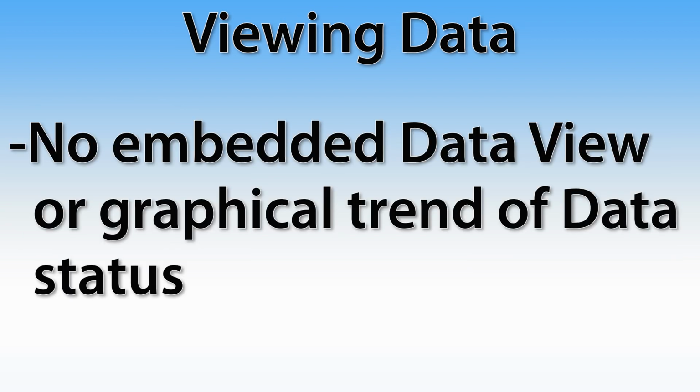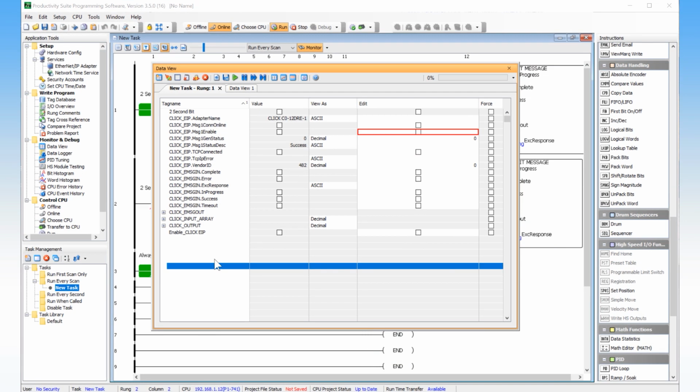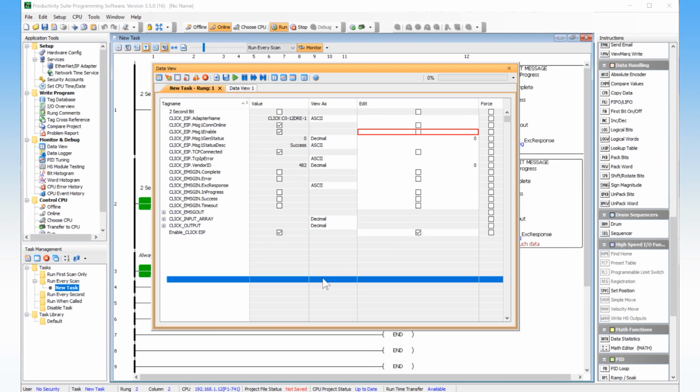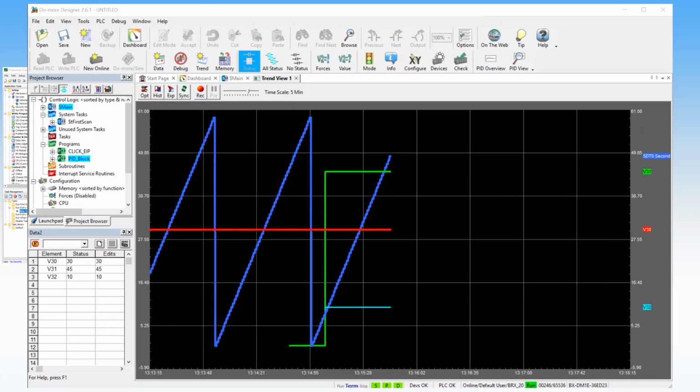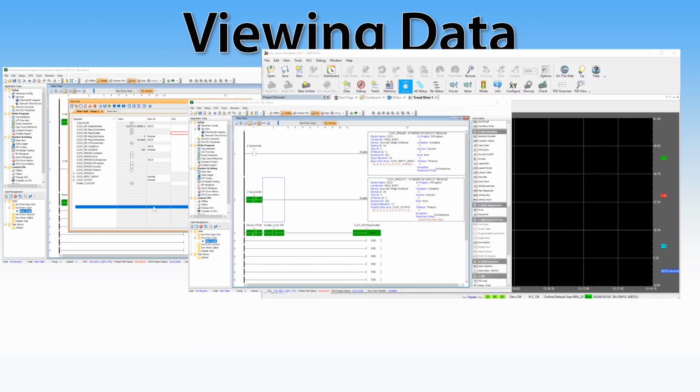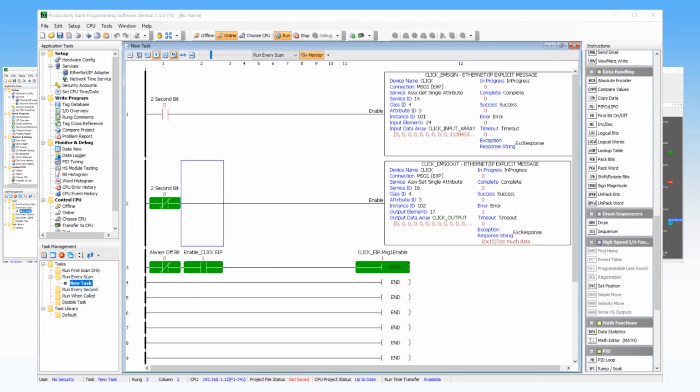Next is that the Arduino does not have a true data view or monitoring like there is in a PLC. With a PLC, you can get connected to the PLC, set up tables to monitor the current values of variables or I/O, and also monitor the status of the ladder code from the development window, which is a huge help when testing, developing, or troubleshooting your system. These tools are all part of the PLC and do not require any extra code being developed to do so.